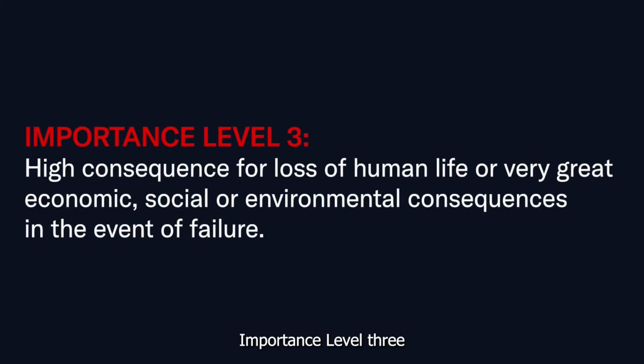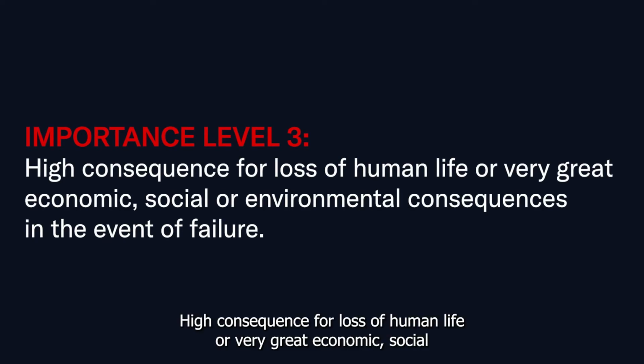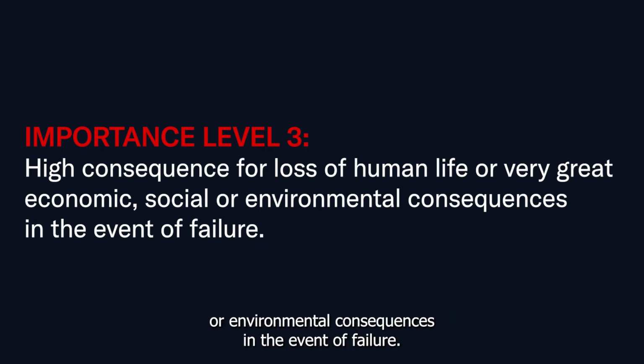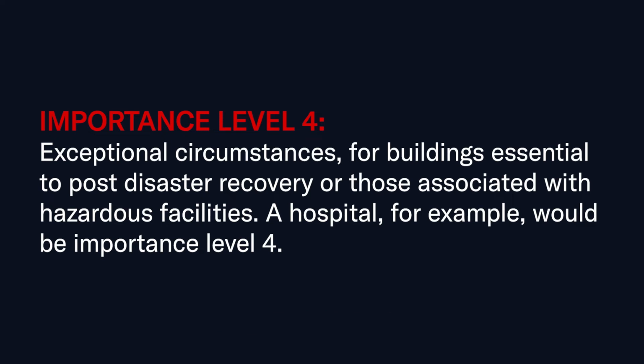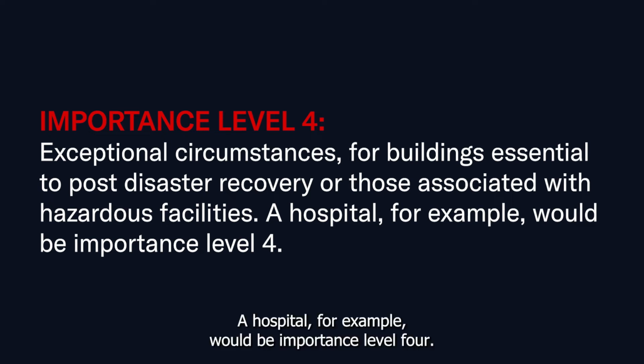Importance level 3, high consequence for loss of human life or very great economic, social or environmental consequences in the event of failure. Importance level 4, exceptional circumstances for buildings essential to post-disaster recovery or those associated with hazardous facilities. A hospital, for example, would be importance level 4.